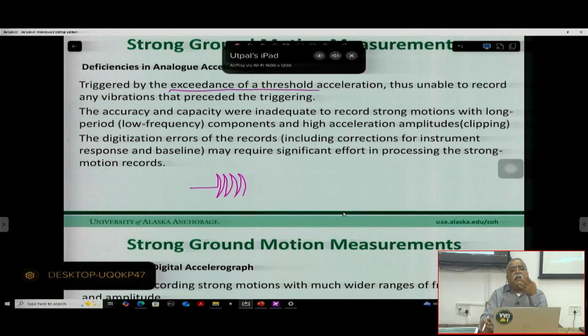And if it is a very strong earthquake, then it will be recorded, and then they take out that film recorder, process it, and do the correction. We have to make corrections like this, so it all becomes a straight line, and then we put a strip and read each and every value at the second interval or the millisecond interval, whatever you need. But it's a very difficult operation, first of all. The second is this,